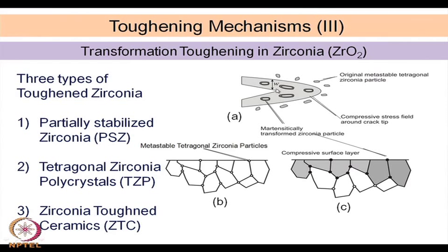Okay. So, normally the crack will try to open up with a tensile load. However, because of this transformation and the volume change, and that transformation is also induced by the stress field ahead of the crack tip. So, everything is quite associated, coordinated, or related to each other.